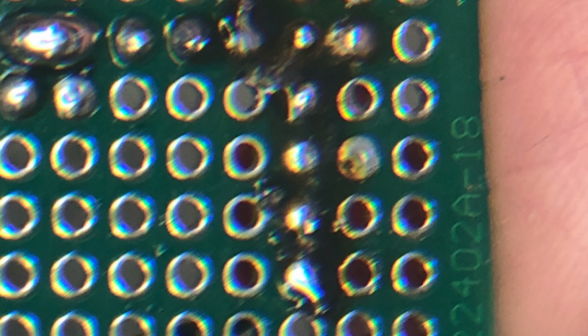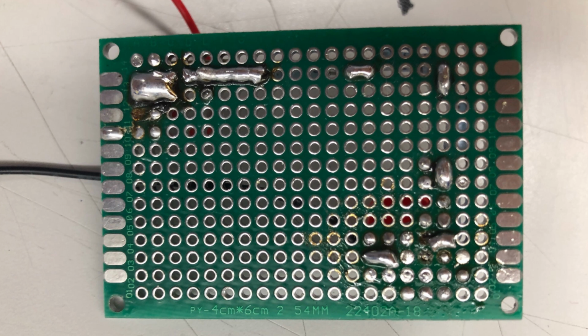If you notice brown residue on your board, that's okay. It's simply the flux from your solder. Flux helps to clean your components and help things connect better. This is what the back side of my proto board looked like after I was done. Your solder bridges will most likely turn out messy, but that's okay as long as there's strong connections.